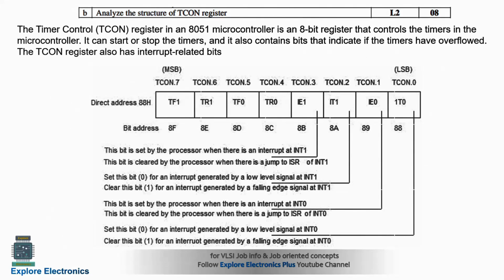The next question is on TCON. TMOD, TCON are very important registers, so you may get this question in your exam. TCON register is also an 8-bit register in the microcontroller. This controls the timers in the microcontroller. It will be used to start as well as stop the timers, and it also contains the bits to indicate if the timers have overflowed, and interrupt related bits are also there.